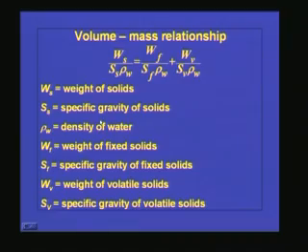Now we have seen that there is a lot of water present, and there will be different types of solids present in the sludge coming from various treatment units. For example, the sludge from an activated sludge process will have both volatile organic matter as well as fixed suspended solids, that means organic and inorganic. When we design a stabilization system or a biosolids treatment system, for the inorganic solids we are not going to do anything, because we cannot remove them from the system; that volume will remain as such. But the volatile solids, or the organic solids, we can remove by biological treatment systems or by chemical treatment systems.